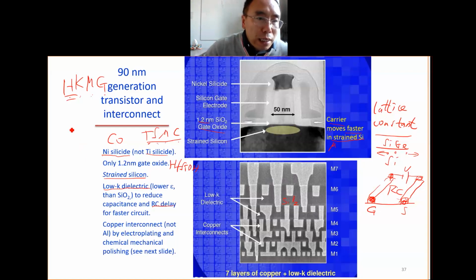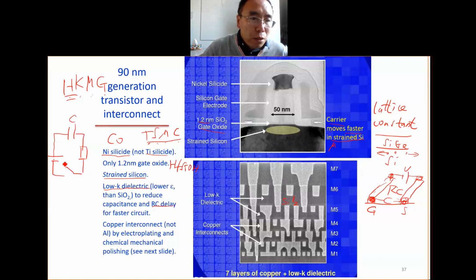We can draw something like this. So we have this capacitance. This is the parasitic capacitance. If we look at the wire, the metal here, there will be some capacitance between those two metal wires. Then we have the resistance of the metal, then the switch, then the voltage. This is the switch, this is the resistance. If we switch this on, we want to know how fast the capacitance will be charged with Q.